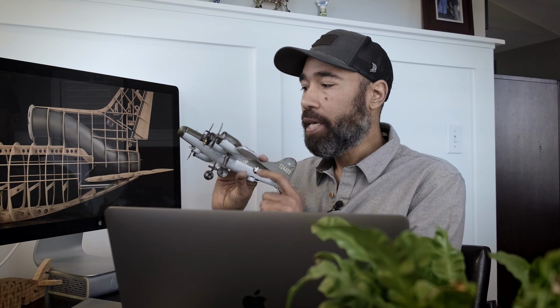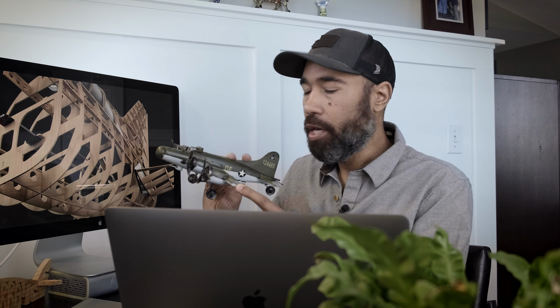Now the other part is when I'm at a high angle of attack, the root will begin to stall before the wingtip. And this is very, very important for the overall performance and handling of your plane. If you're at a high angle of attack and the root starts to stall, you don't want your wingtip to stall at the same time. You want to make sure that the wingtip is still producing lift or maintaining laminar flow over the surface of the wing, so that way you still have aileron authority in a stalled condition.